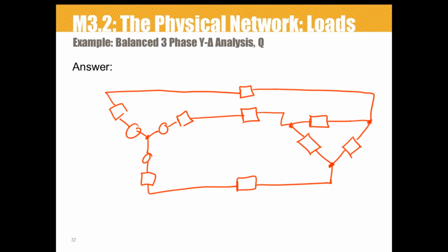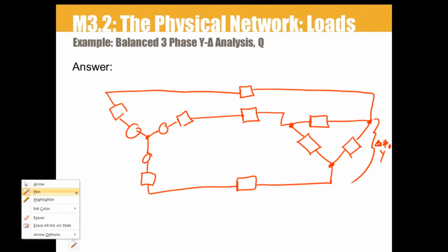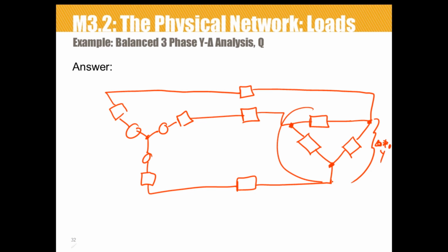The load's connected in a delta shape, and what we want to do is use the delta to Y transform here. That's the technique: we need to replace this portion with a Y equivalent circuit.